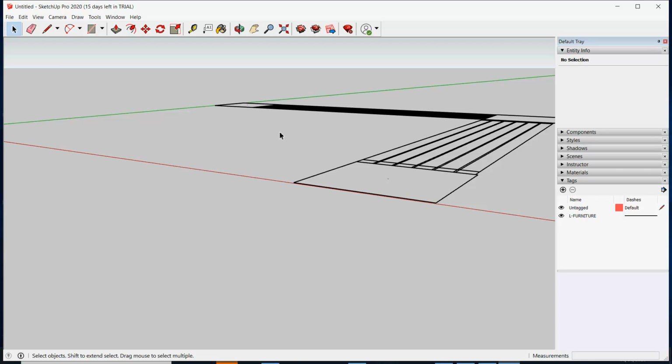We suggested that you should always check sizes, so I use the measure tool and measure from one side to another, and I get surprisingly a value of 10,160. That's clearly not correct. I couldn't work out what was going wrong, but I'm told when reading up that there's an easy way to scale a model so that you get correct values.